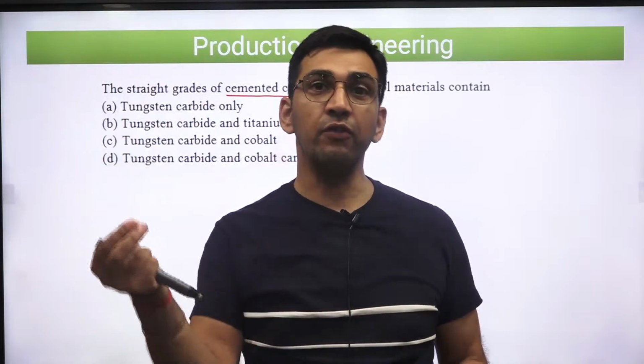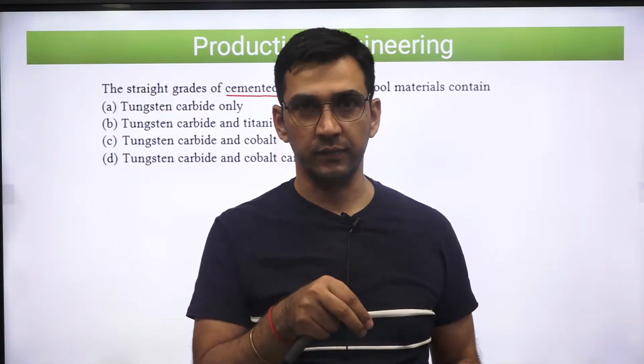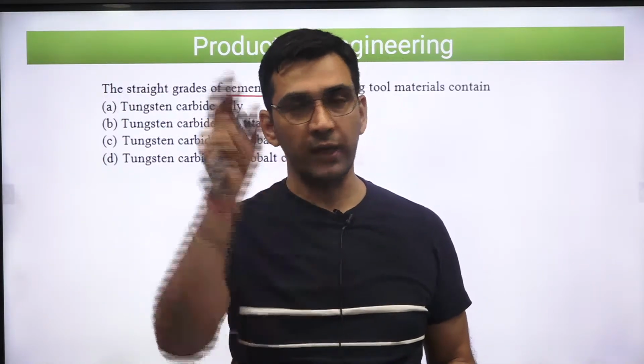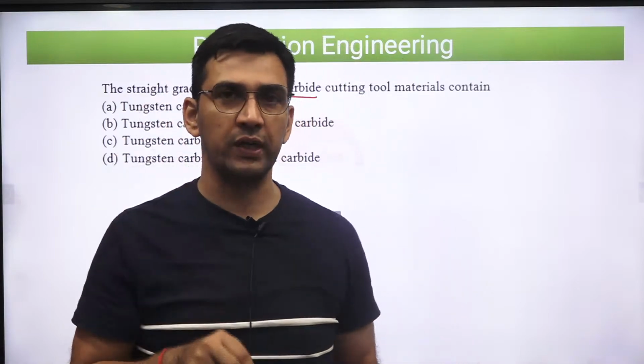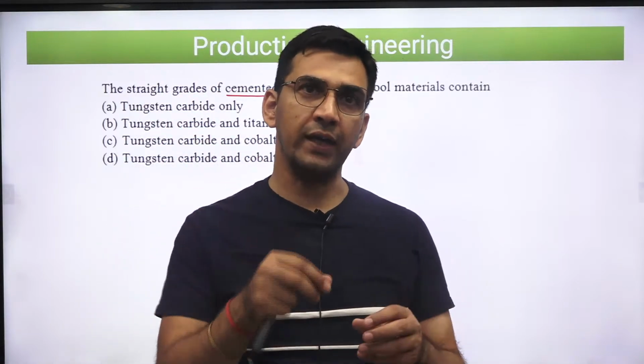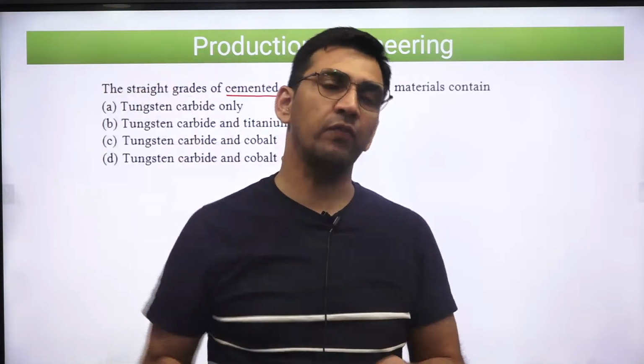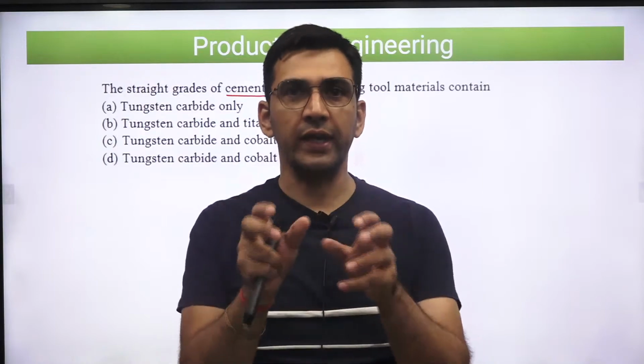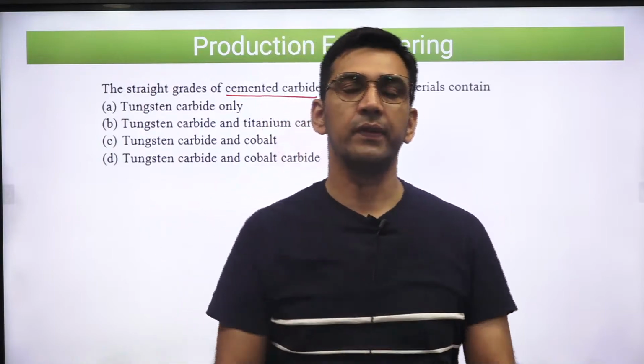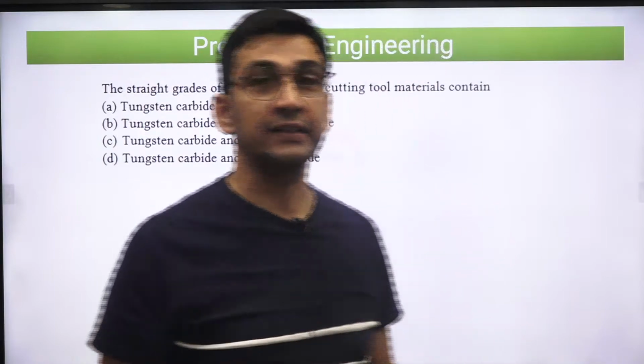So what I will do, I would add some other material like cobalt. इस केस में कोबाल्ट को ऐड किया तो कोबाल्ट का मेल्टिंग टेम्परेचर इज सिग्निफिकेंटली लो कंपेयर टू दैट कार्बाइड पार्टिकल्स. सो जब वी विल रेज द टेम्परेचर ऑफ दैट होल मिक्स अप टू द मेल्टिंग पॉइंट ऑफ दैट पर्टिकुलर कोबाल्ट, तो वो बाकी पार्टिकल्स को पकड़ लेगा. सो इट विल एक्ट एज ए बाइंडर.